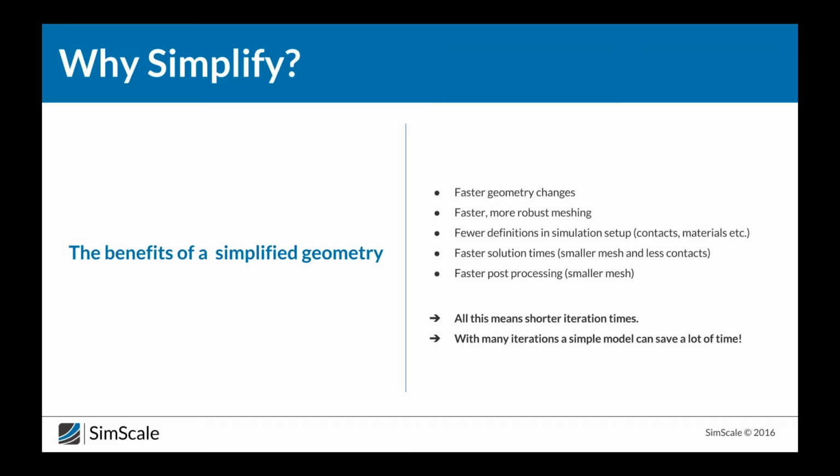So when you look at the full cycle of simulation, there's the geometry change or preparation, there's the meshing, setting up your simulation with contacts and materials, and so forth. Then there's the actual processing time, and then there's the post-processing time. And each of those stages are impacted by the original geometry. So the simpler and the cleaner that geometry can be, the quicker each of those stages will be.